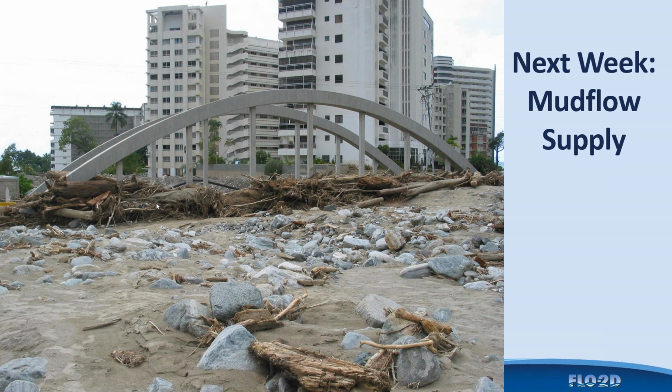When we add volume in the hydrograph, what coefficients do we use? Again, you need to go to the table and have a physical sense of what you think the mud flow will behave like. Is it wet cement, or is it kind of like a muddy flow of water, or is there very little clay in it, and so forth? And then base the selection of the parameters on that type of event. And that's regardless of whether you do the concentration by volume or the actual volume in the mud flow.